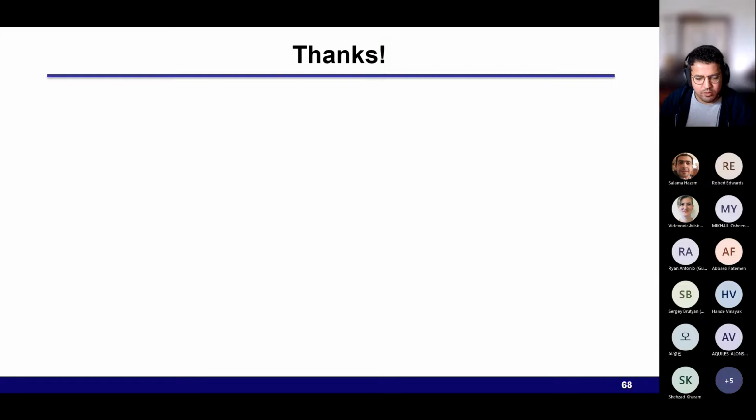Especially on corners, at ambient temperature you still get some good results. I have a table which is actually publicly available, but at -40 and 120 degrees, you get wild results, completely off. The reason behind that, I'm suspecting, is basically that the models are not great at those corners. So we're trying to improve that with NIST. But there might be some extraction issues.